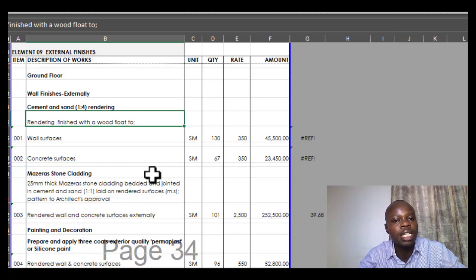Before I forget, you also need to do it net. For example, if it's walling, that area should be net, implying that you need to deduct items that are not making up the wall, including the openings. Okay, so in that case you have all the sections that we've covered today, right?